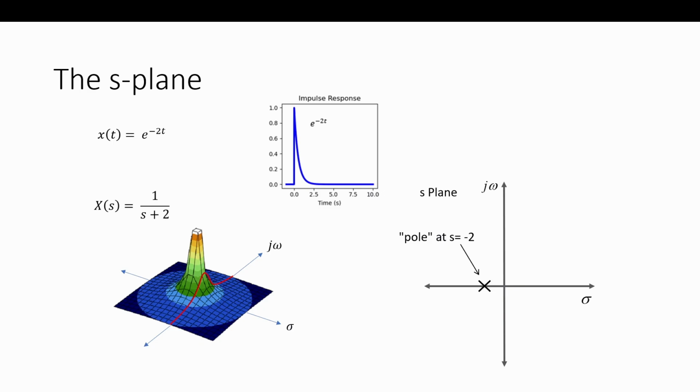If our function itself in time is e to the minus 2t, and then we go through and we try every possible value and we put it into the Laplace transform function, which is correlating to x of t, when we set s to be minus 2, you'll see that function will go to infinity, will explode, right? And that tells you, I look at that and I say, oh, your function is e to the minus 2t, because that's the s where it made the pole.